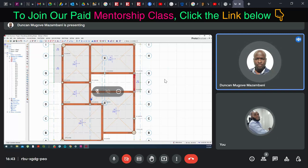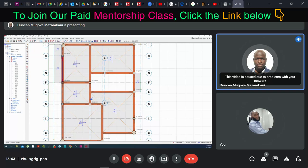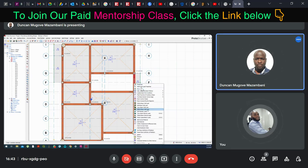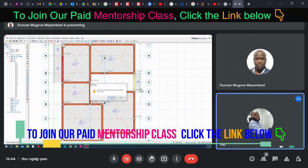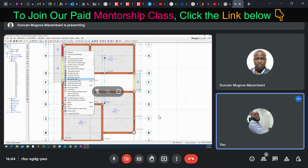Okay, the wall load on this one. Yeah, it should be removed, and also these two here. Exactly. So do that and remove the wall loads on that area. So I have to click here and right click. Yeah, right click and then say delete beam wall load. Exactly. Okay, then I do the same here. That's fine. And I do the same here. Okay, that's fine.